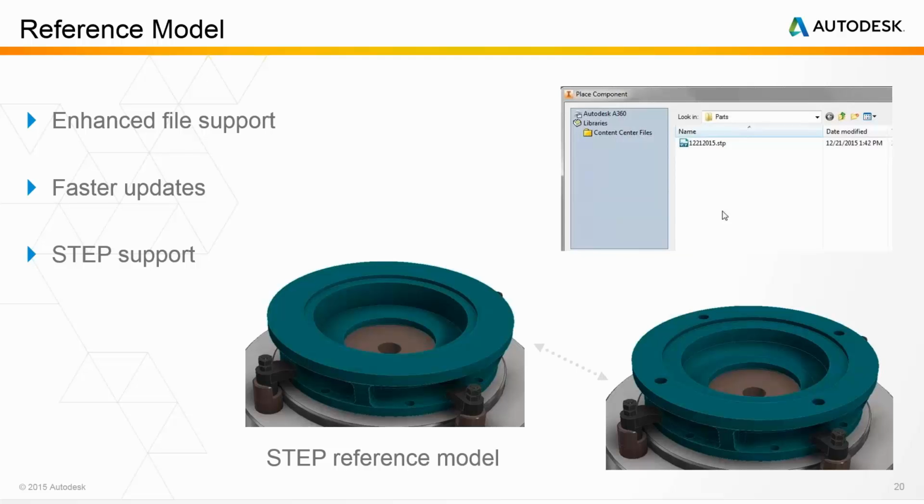Secondly, any way that you use the geometry, whether it's using it through constraints that you're adding or references, or maybe you're running CAM toolpaths or you're running simulation, the setup time and the investment that you put in place into using that geometry isn't lost if you have to re-import it later on. All you're doing is re-referencing the data. So it's effectively a live link to the file. Now this works on a range of different third-party file formats, including CATIA, SolidWorks, NX, ProE, and Creo.